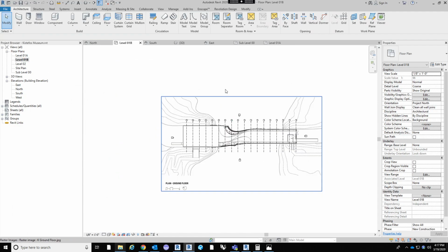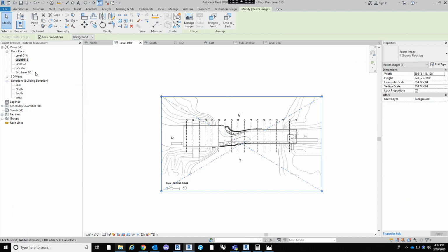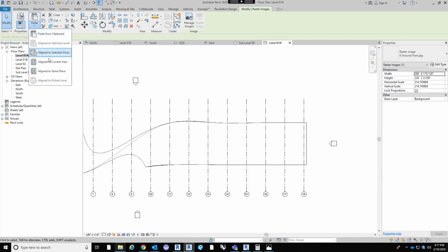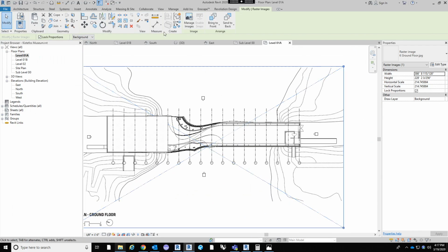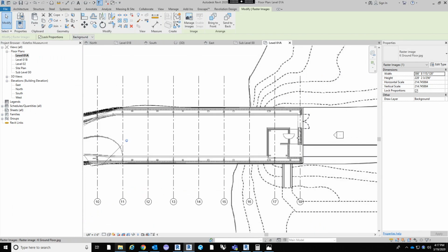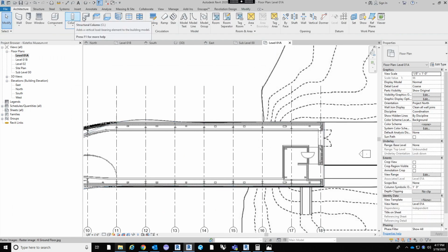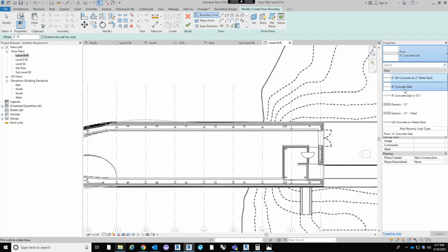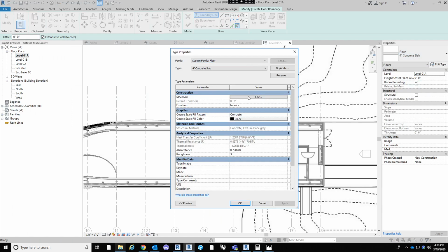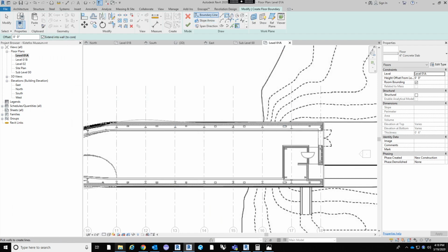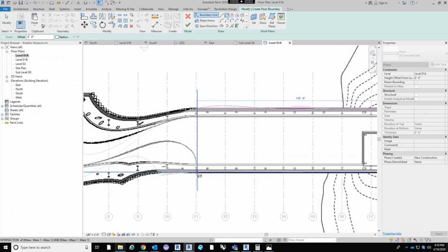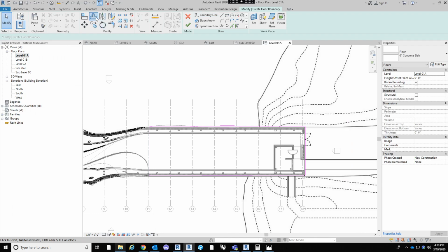Let's go in and copy this image. So we have some guidance. Remember to pin it so it doesn't move. And then do same floor. 6. Ooh. One thing we forgot to do, rename it. So rename this 6-inch slab, concrete slab. It's okay. Do the same thing. Go to grid line 11. That's where it starts to transform. And then offset in 1 foot from each exterior.